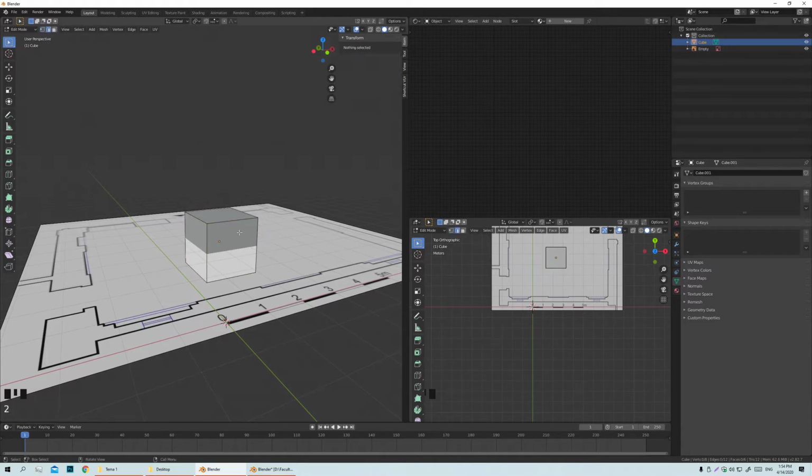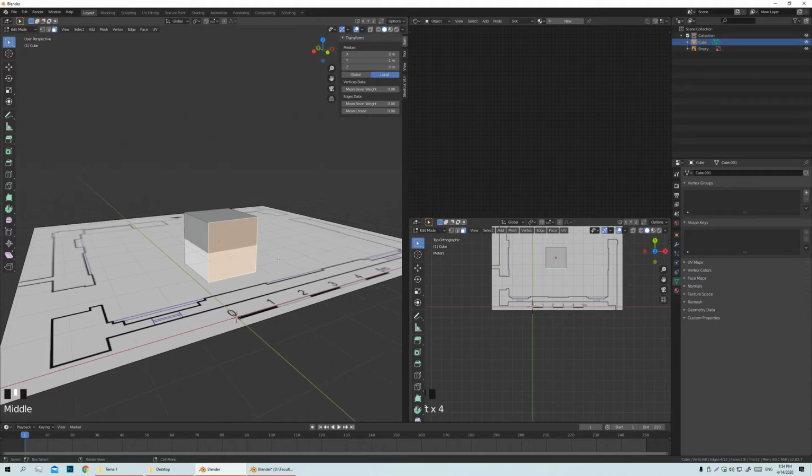When you press 2, it's edge manipulation, and when you press 3, it's face manipulation. Okay, so we'll just keep the faces on. So let's go ahead and press G on the Z-axis by 1 meter. Oh, sorry, I had to select the whole cube. So G, Z, 1. Okay.